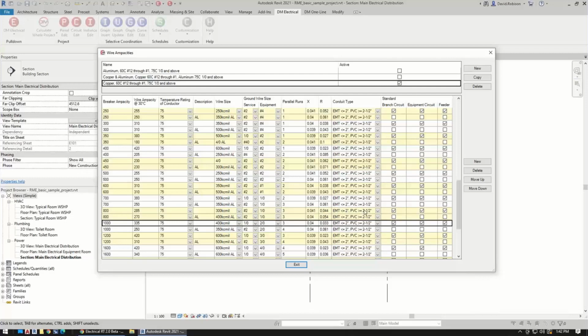Next column is the conduit type. This is where you can choose from those groups of conduits which one we're going to use for our automatic sizing. By default, everything's using this EMT PVC combo choice. But if you always wanted to use EMT for a configuration, or always PVC, or this one doesn't have a wire conduit at all, you could just go in a cable tray or something. You could specify that here. And then when we're choosing the conduit, we're going to choose from those options.